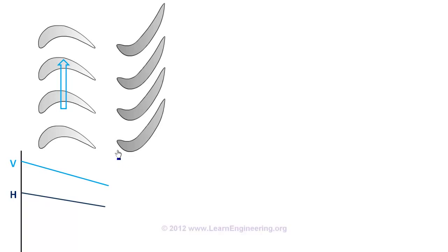Stators are also a set of blades, but these blades are stationary. They won't take part in energy transfer. What they do is simply transform energy from one form to another. Or more precisely, they will transform the enthalpy energy into kinetic energy. You can see the cross-section area of the nozzle decreases with flow, so due to its special shape the velocity increases. But at the same time enthalpy decreases. If you sum the change in enthalpy and kinetic energy, there won't be any change.